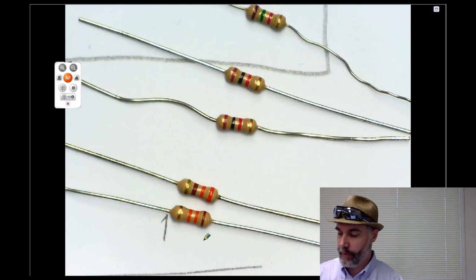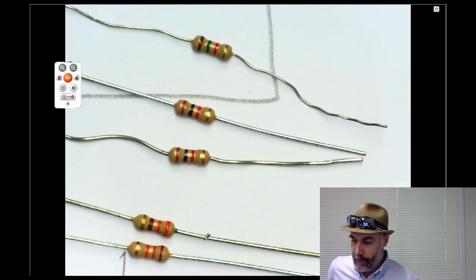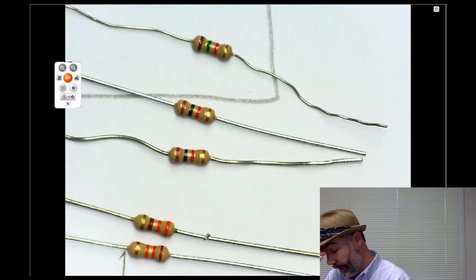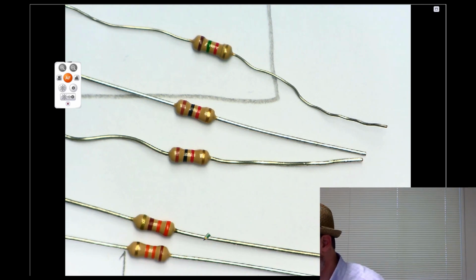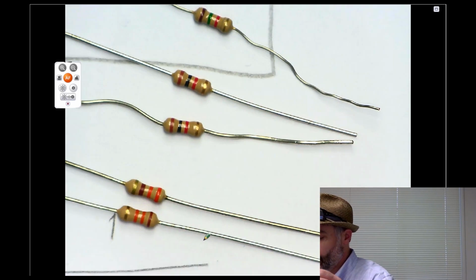That one at the top now is the brown, green, and red. The other thing you can do that can be helpful sometimes is you can shine a light on the resistor, or if you have a cell phone, you can take a close-up picture of the resistor, and that can help you to see what's going on. But if you're not sure, the final say is always the meter. Okay?